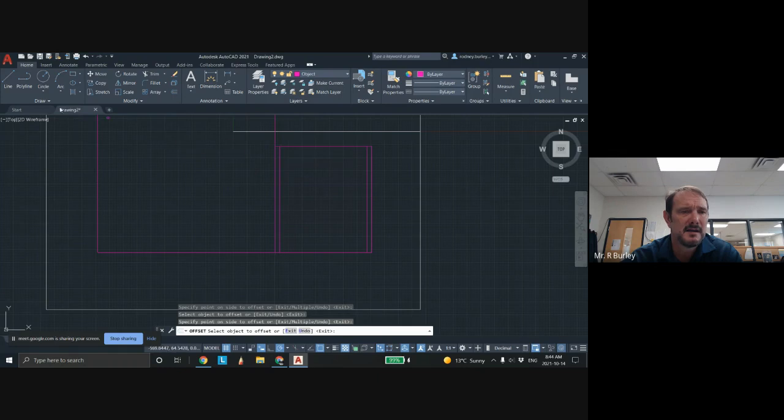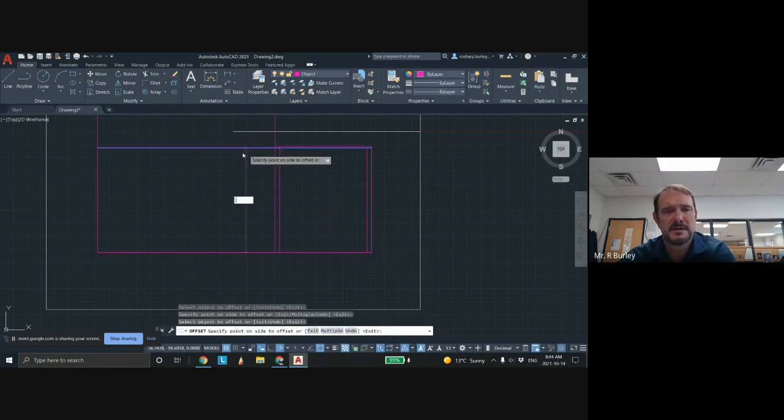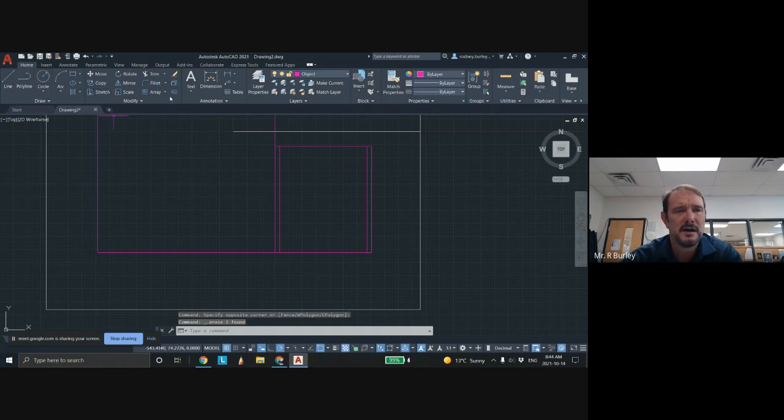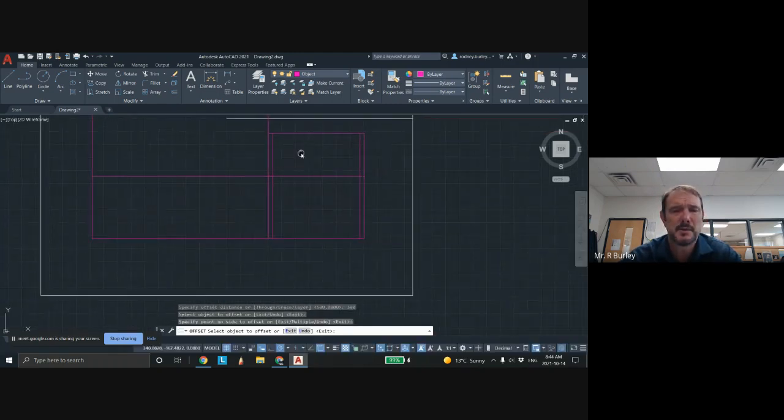And then I could say, let's bring a line from, I don't know, line tool. Let's offset again. And this dimension from here up, I don't know. Let's say that's 1,000. Or let's say 500 maybe. 500 is a bit tall. So I delete that. A little trial and error here. Hit the escape key again because you're locked in command. Delete. Offset command here. And let's say 300. Enter. And make the top of the garage door 300. There we go. That's better because now you have a space in the top to put bicycles and stuff.